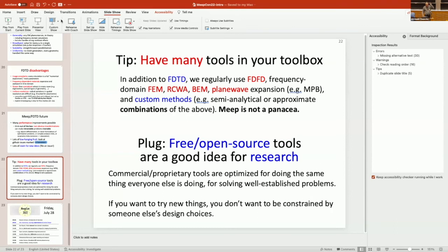So of course you can check general properties like conservation laws and other things. The first thing you do is you just run it and see if it looks right, because usually your first pass isn't working at all, and the solutions blow up or do something crazy that isn't right. Once the solutions look more or less right, you can check against analytical solutions. There are analytical solutions in a handful of cases, and that's really useful to check against, especially when you're first starting your first tool.